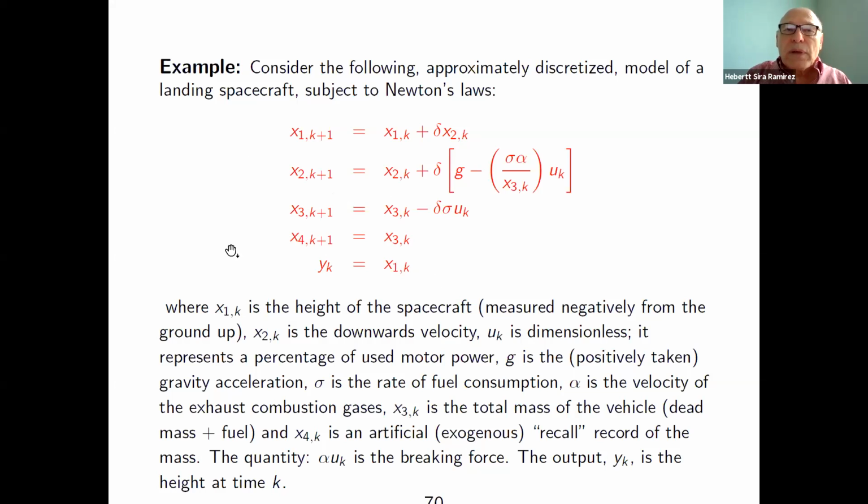Even though in principle you cannot see the immediate effects of that instability in the output, because the output is somehow decoupled from these dynamics. Control depends on the variables defining that zero dynamics, and therefore the control design is very much attached to the characteristics of that zero dynamics.